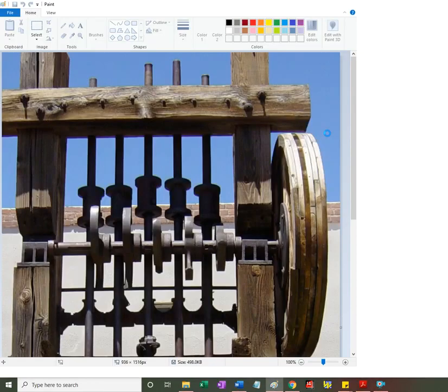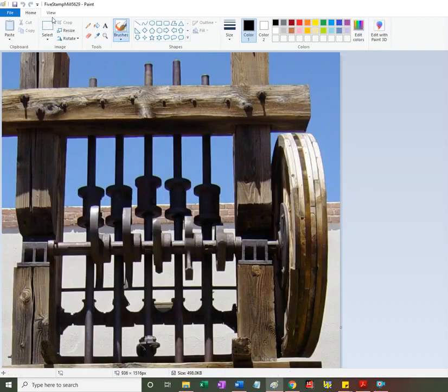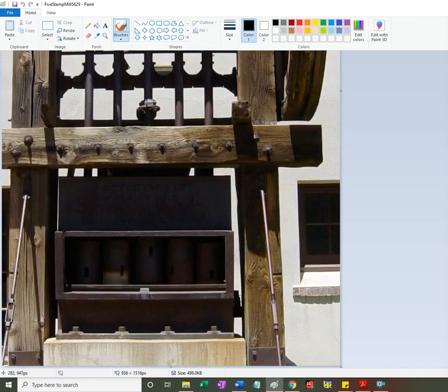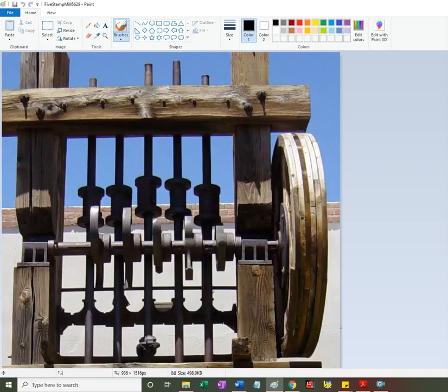There's the stamp mill used in ore processing, and this is a shaft that's supported on two bearings, driven by a belt and a pulley. And in this type of cam, contact between the cam and the follower happens only for a portion of the cycle. Each of these rams drops under its own weight. They're heavy, and what they do is crush ore down here below.